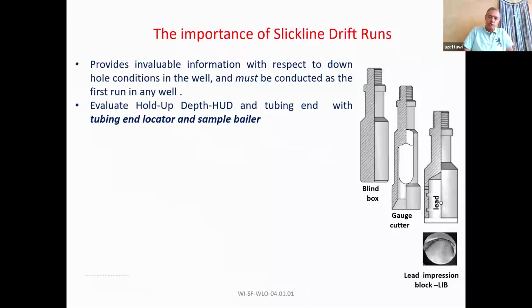When we go to coil tubing, the API responsible for the pressure control equipment and operations is API RP 16ST. RP is always recommended practice. 16ST tells you that when we come to the pressure categories, the first category is category 0.